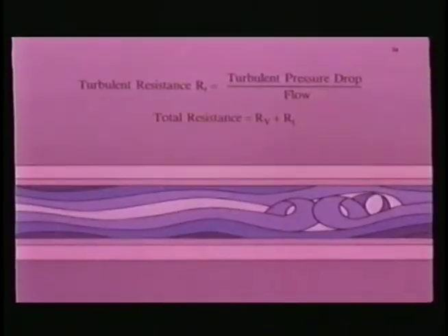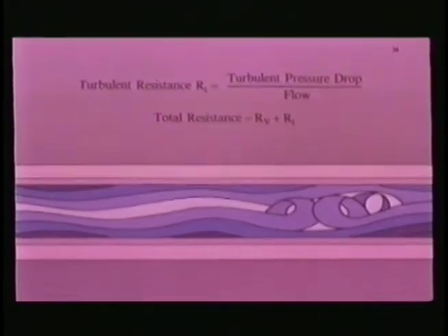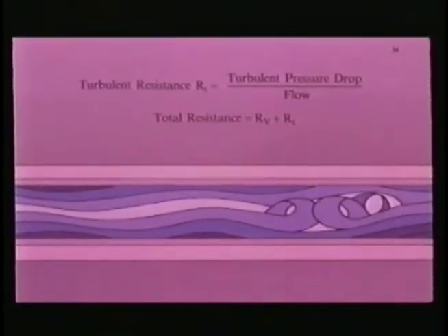34. The ratio of the turbulent pressure drop to the flow rate is referred to as turbulent resistance, RT. During turbulent flow, the total resistance is the sum of the viscous resistance and turbulent resistance. When the flow rate increases, turbulent resistance and turbulent pressure drop become increasingly important.